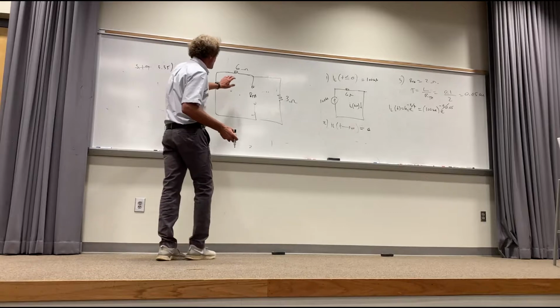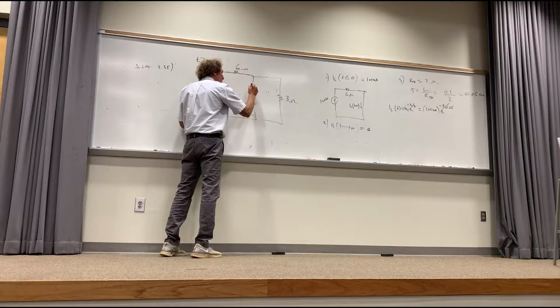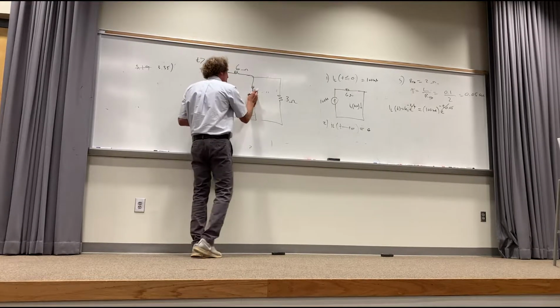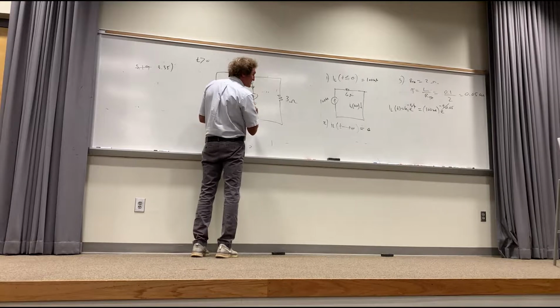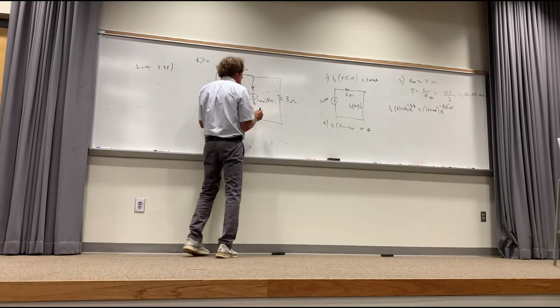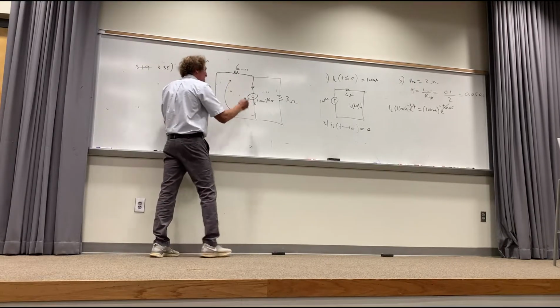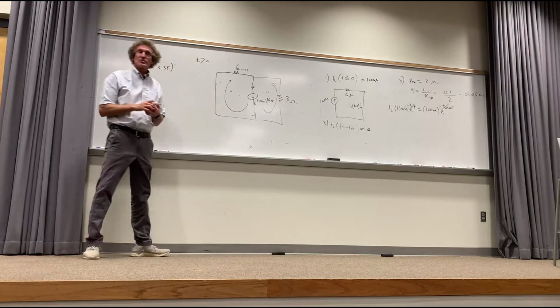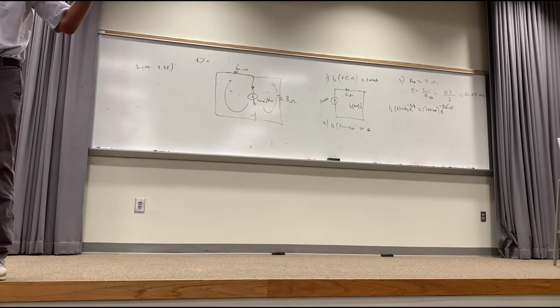Through this one? Yeah. Alright, now let me just show you. So I got here flowing this way, really it's going to be right here. So let's see. I have here a current equal to that, which is really 100 milliamp e to the minus t over 0.05. That's the current flowing here. Do you all see that? Now, some of it goes this way, and some of it goes this way. You see those 2 resistors are in parallel? How many see that? If they're in parallel, can't we use current division?